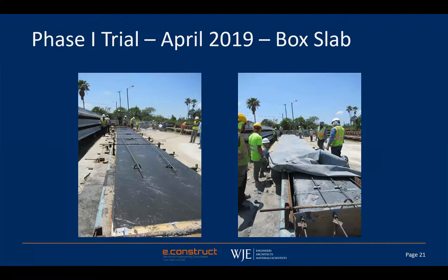All right, so this is what it looked like when it was finished before they covered it up for curing. You may be aware that some UHPC is steam treated after curing to encourage hydration of the silica fume and the other cementitious materials. But in fact, the warm ambient temperatures in Florida can also aid the hydration process without the need for external heat. So the internal temperatures in this particular product reached about 180 degrees just with that ambient heating.